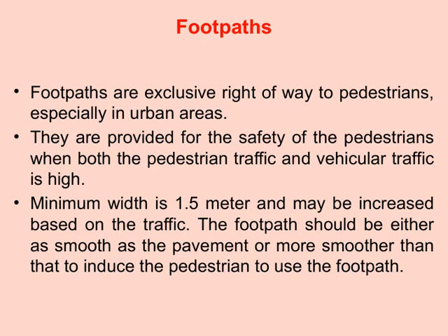Let's talk about footpaths. Footpaths are essentially the exclusive right-of-way for pedestrians, especially in busy urban areas. They are designed to keep pedestrians safe by providing a dedicated space where they can walk without having to worry about vehicles. When both pedestrian and vehicular traffic are high, footpaths become even more crucial for safety. The minimum width for a footpath is typically 1.5 meters, but this can be increased depending on the volume of foot traffic. The goal is to ensure comfort and safety for everyone.